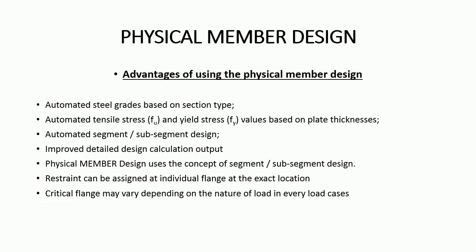So this flange on the top part of the section can also act as the element which can take the tension. This can happen when the load acts upwardly, that is, in the opposite direction compared to the earlier case. In this case, the lower flange is under compression, and hence in this situation the critical flange has been reversed. And in this case, the lower flange is to be treated as the critical flange.